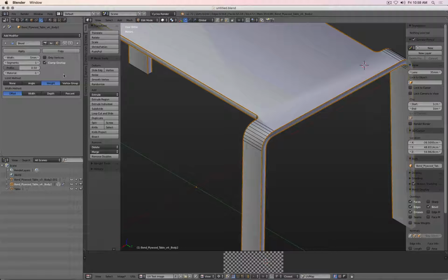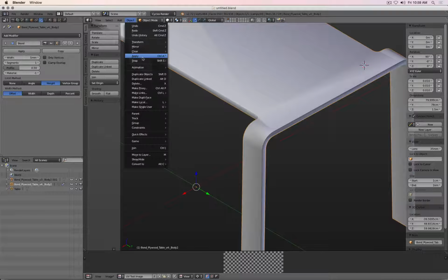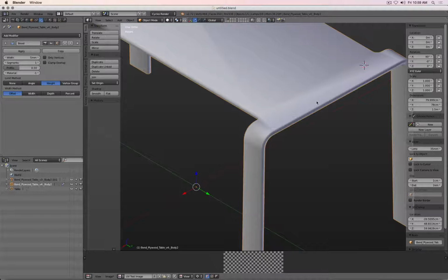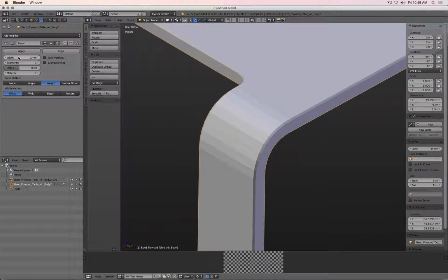And nothing really works. And that's very simple to explain why. Simply because this object has a scale factor. So I have to apply the scale factor right now. Apply scale, zip, and shade flat. And there we see, for example, the bevel. So if I say this one 2 millimeters, there it's smaller. Maybe instead of chamfering, make it a fillet. So nice and round.